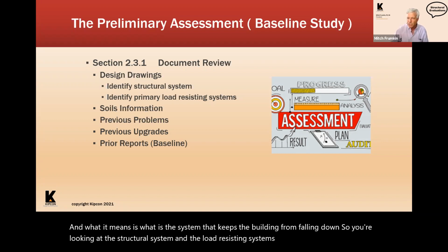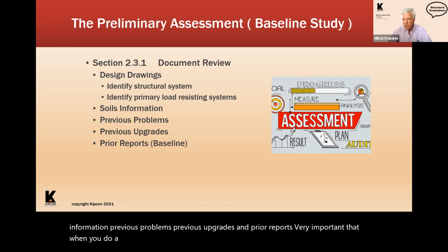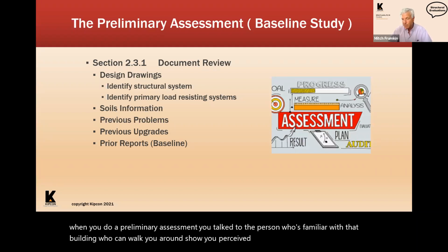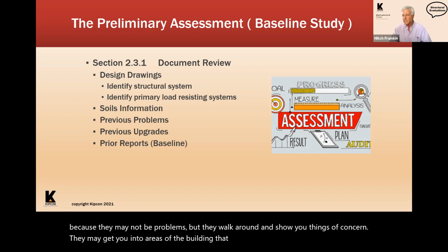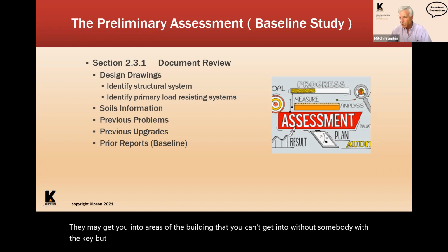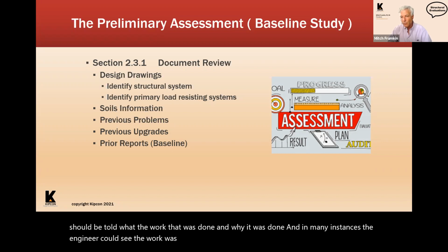You're also looking at soils information, previous problems, previous upgrades, and prior reports. Very important that when you do a preliminary assessment, you talk to the person who's familiar with that building, who can walk you around, show you perceived problems. I say perceived problems because they may not be problems, but they walk you around and show you things of concern. They may get you into areas of the building that you can't get into without somebody with a key, but they show you around the building. If there is any work done to the building, you should be told what the work was and why it was done.